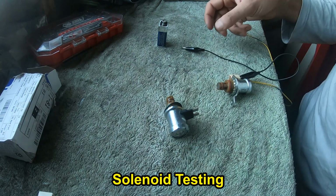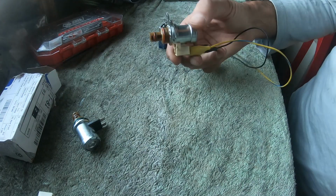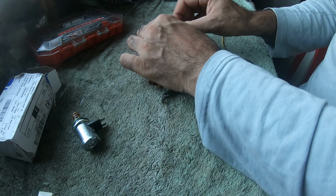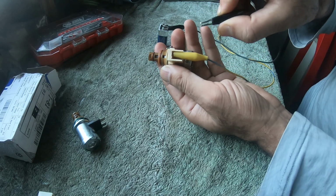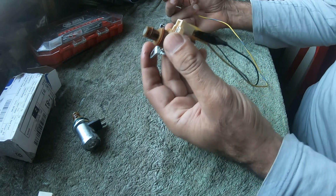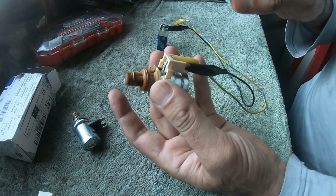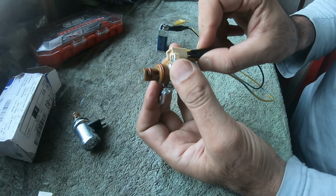So in this test, what I'm going to do is provide some voltage to these solenoids that I have removed. To do that, I'll use the positive terminal, and if I hold it like this, I'm going to provide it to the left side. Okay, so positive terminal goes to the left, negative goes to the right, and I'll try to hear the clicking. There is some sort of clicking I can hear, but it's very inaudible. You have to really pay attention to it.